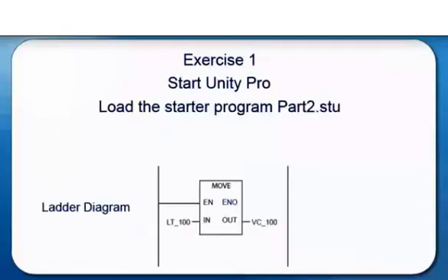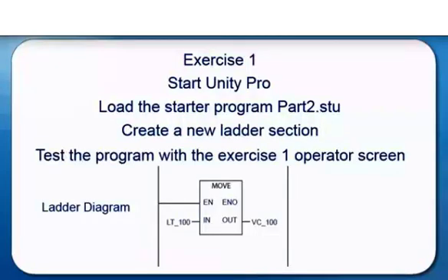Start Unity Pro, load in the Part 2 starter program, create a new ladder section, place the move on the screen with the input of LT100 and the output VC100. Test the program with the operator screen exercise 1.